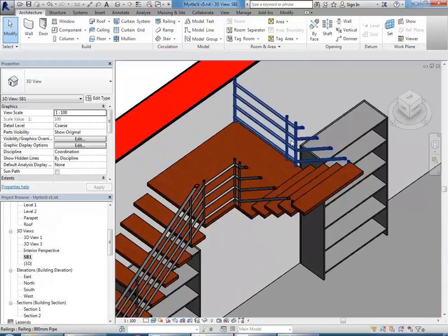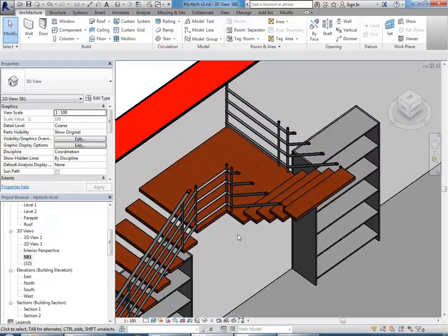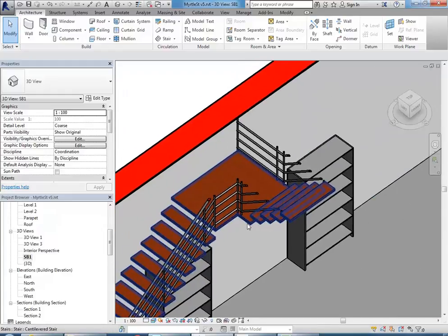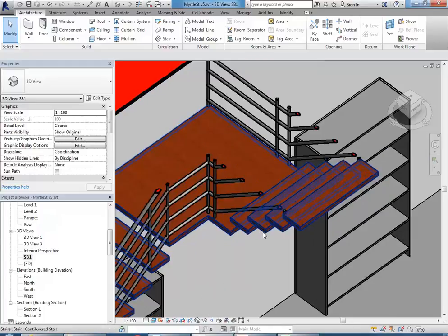So just to finish off there, you'll find often that you need extra components in stairs that are either too difficult or impossible to do just by changing the properties. So in this situation here, if this stair was going up this way, I'd need some sort of support. I couldn't have it floating. So if you want that, you'll need to model those extra things in.